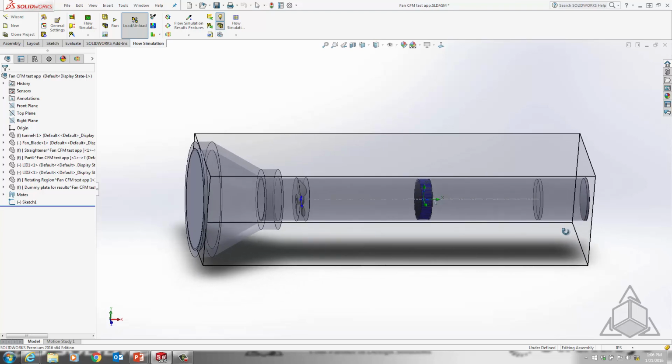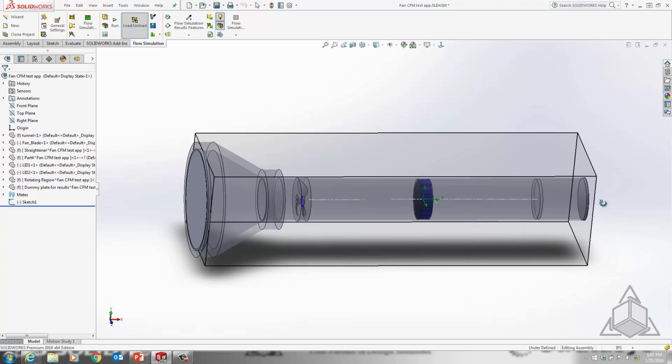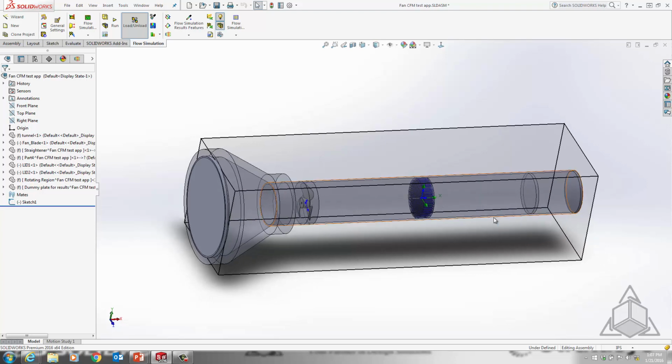For this analysis, we actually don't need to have a throttling device, like a sphere there to control the pressure. Why? Because in the analysis, we can set what the pressure is as it comes out. If it's higher than atmospheric pressure, I'll just set it at a higher pressure as it comes out, and you'll be able to see how the velocity changes. Okay? So let's take a look at how we can put this analysis together.